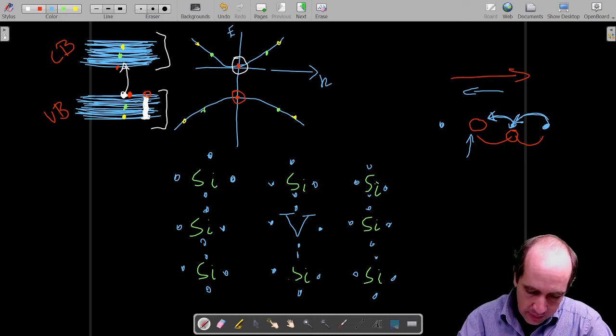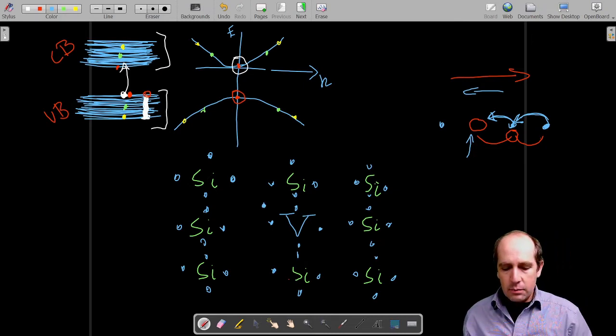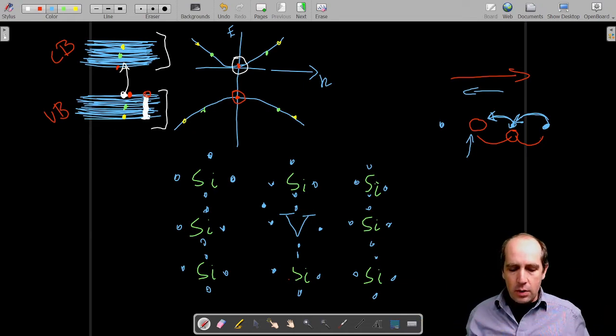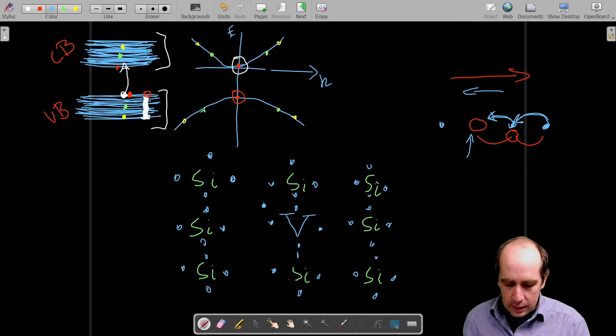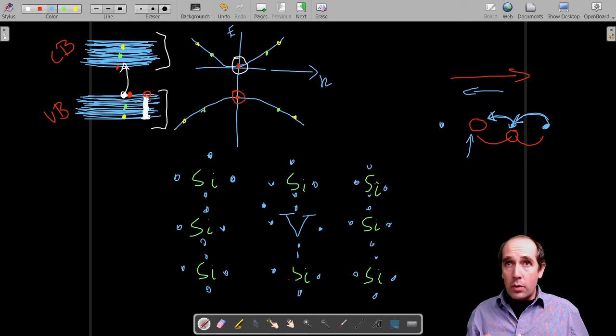And so we will have these 4 plus one additional one that is more or less breaking a little bit the perfect repetition of all this silicon crystal. However, the electron will see the potential not just of its own atom or just the first neighbors or the vicinity. What the electron sees is the potential of the entire silicon lattice, which in principle is infinite. So we have many silicon atoms in all three directions. So what this electron sees, and it is very important to realize, is that all these electrons, all 5 of them, are indistinguishable from the rest of the electrons supplied by the silicon atoms originally. So they're all the same. It's just that we've managed to put one too many, okay?